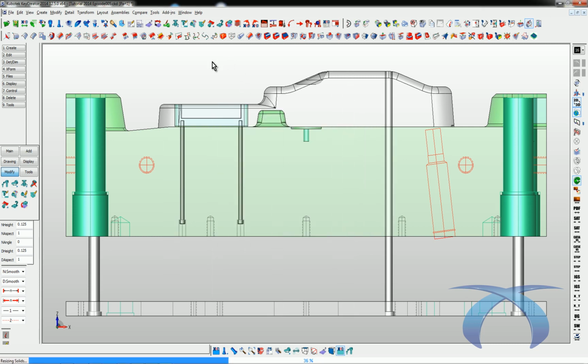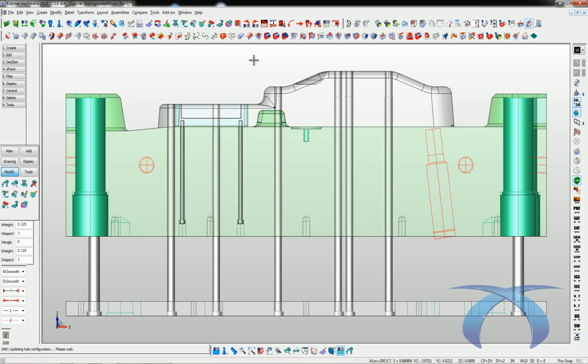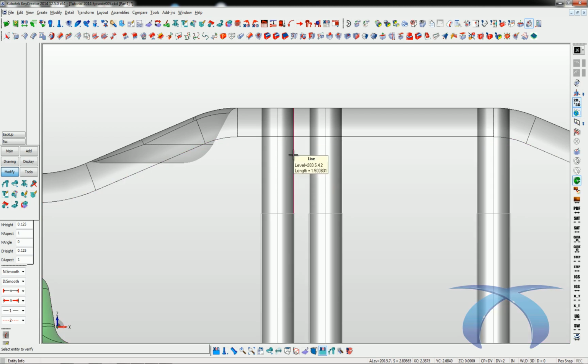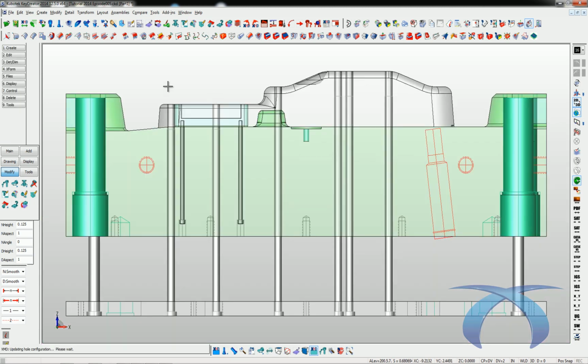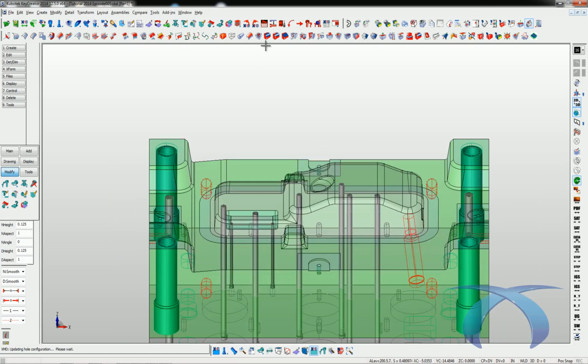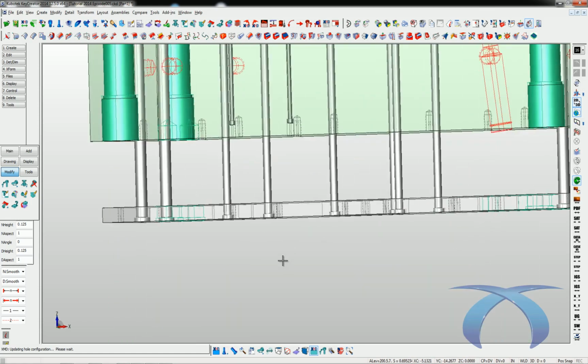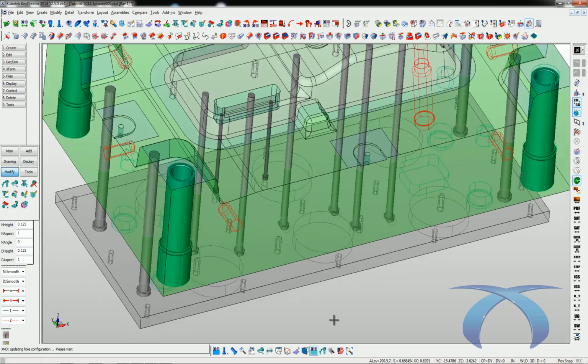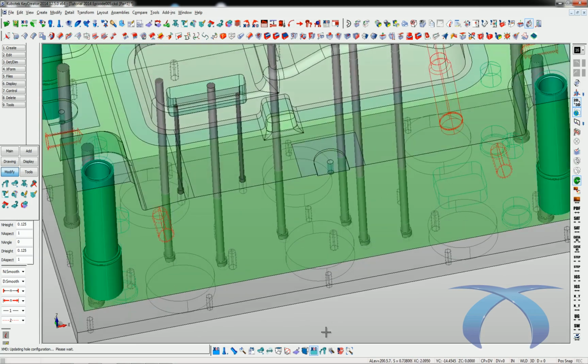And I say okay, and the ream length now is increased for every single one of them by 1/2 inch. So now it's 1.5 inches ream. Now I have the choice of saying single, so I could just change that one, or I could do group, which would take care of ones that are symmetrical about each other in the tool. Right. And so now I have my additional ream because this customer for this particular job wanted the ream increased.